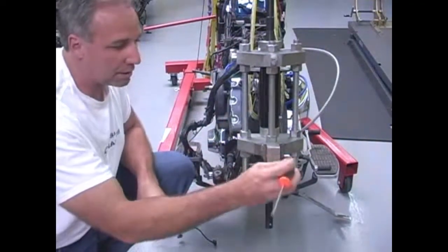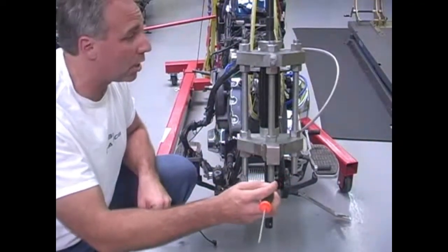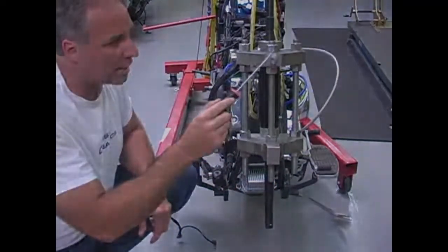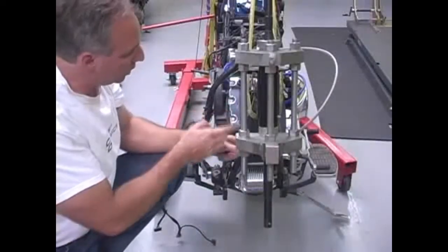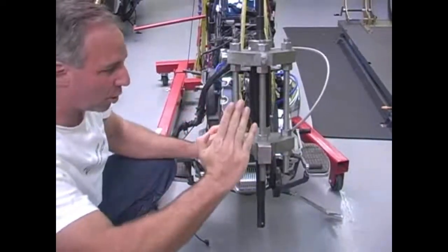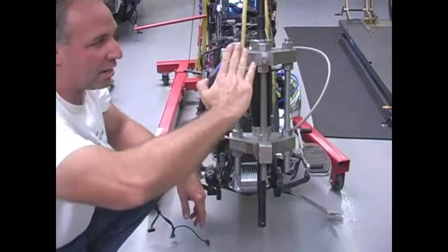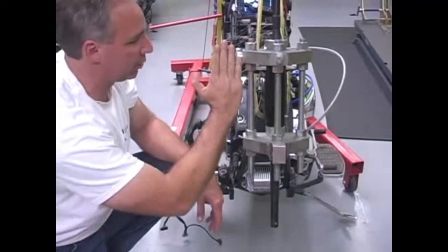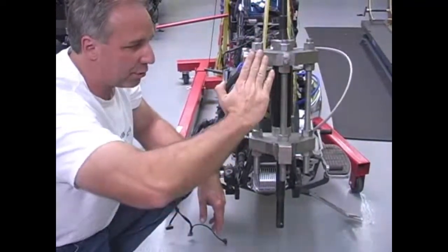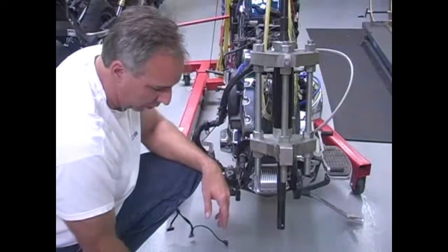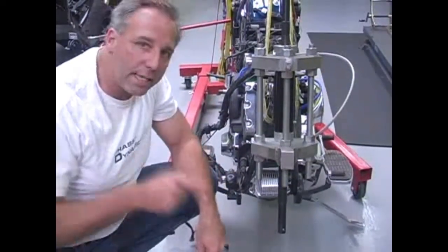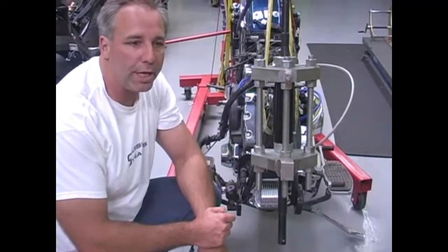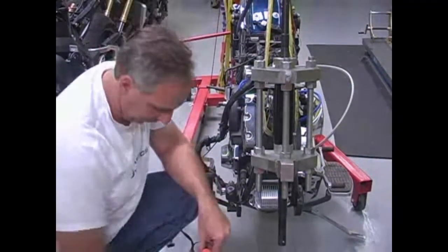I'm going to pull this out, that 1.23 degrees that we've talked about, and almost as importantly, I'm going to be able to hold the top of this, right? That way we don't just pull the whole frame forward. What we basically do is pull an angle into it, because we're 4 millimeters short, we're not 15 millimeters short, so we just need to pivot the steering head axis, and that'll give us our 4 millimeters at the bottom. So the next shot you'll see will be of the bike in the jig, and we'll talk about centering it up in the jig, and we'll begin to straighten it.